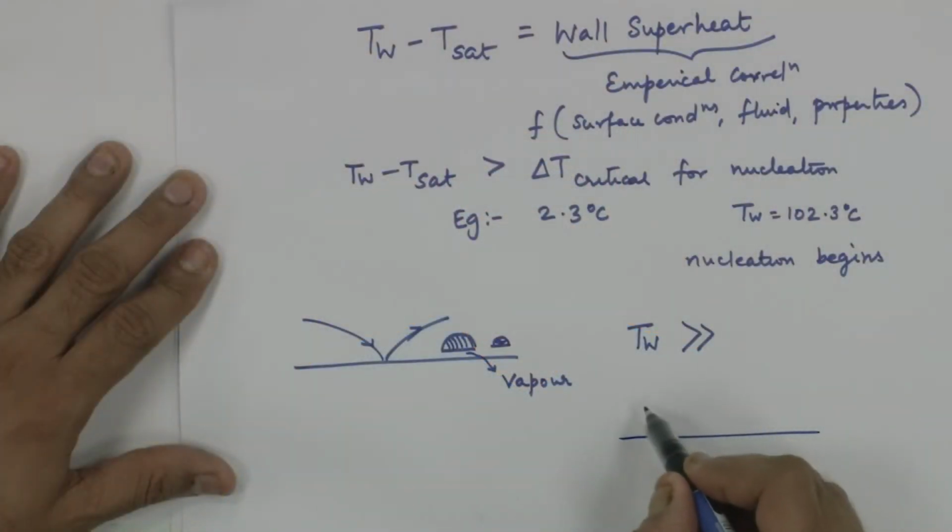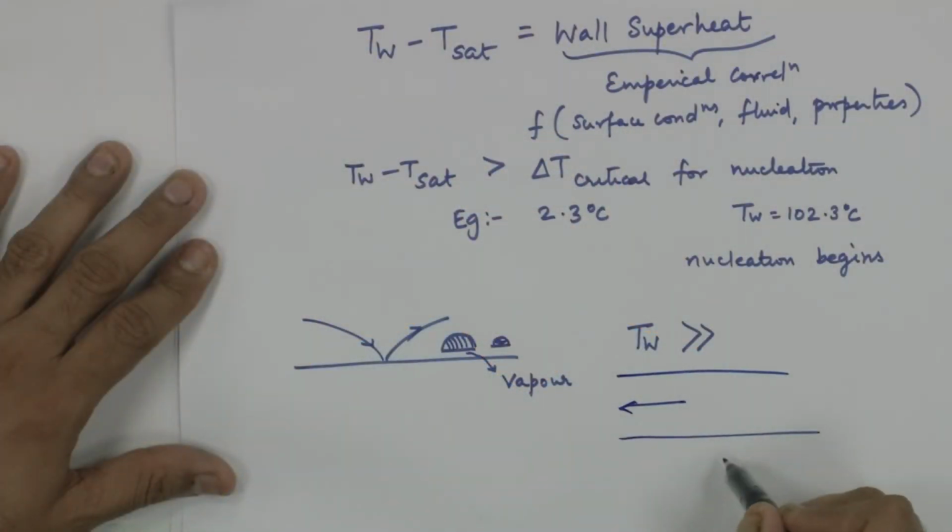That point where the liquid loses contact with the heated surface, because T wall becomes much greater than where liquid can establish contact, is very, very dangerous from heat exchange point of view, from engineering point of view. That point where the contact is lost should never be achieved, because what will happen is, if I have a tube and water is flowing through this, suppose there is a local hotspot.